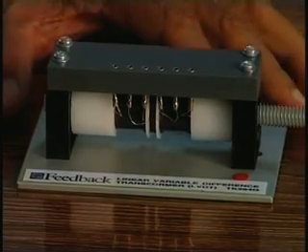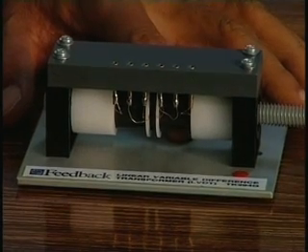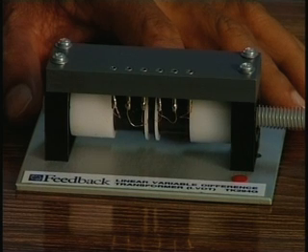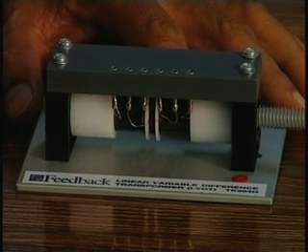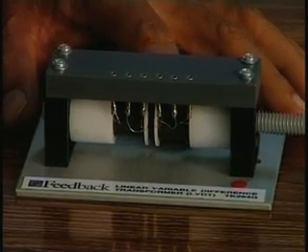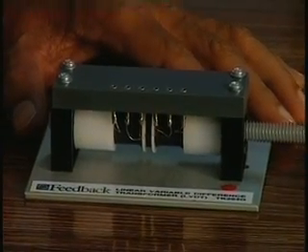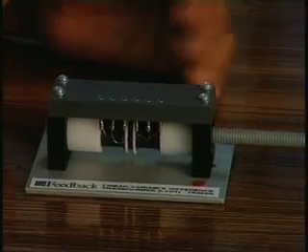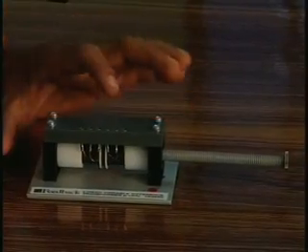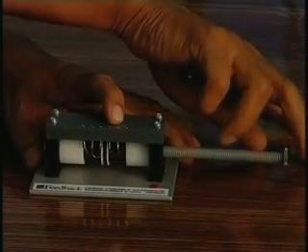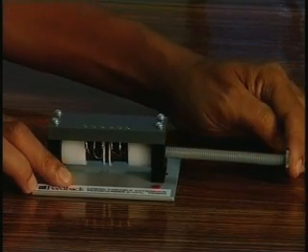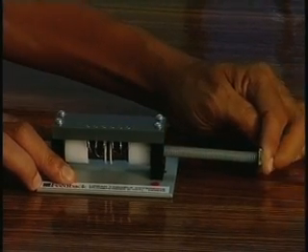You see here, this is an LVDT, linear variable differential transformer. It has one primary and two secondaries. The secondaries are usually connected in opposition to get a null position, and after doing phase sensitive demodulation, I can sense on which side of the null position the core lies. You see here the core is there, a soft iron core, which will move like this. So now I am moving. It will move like this.